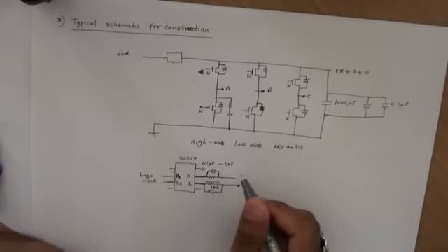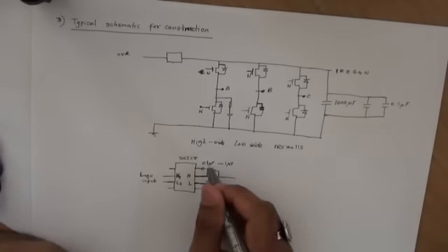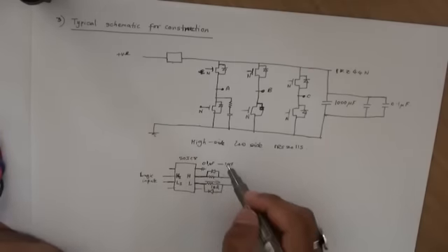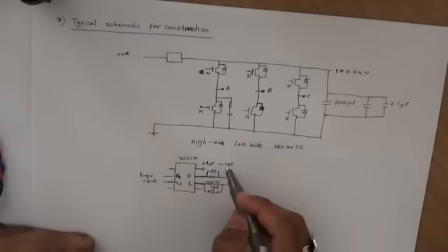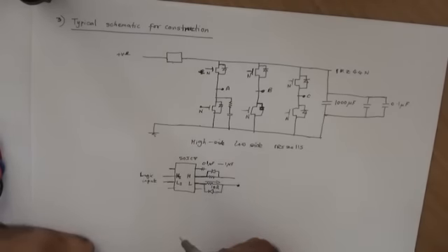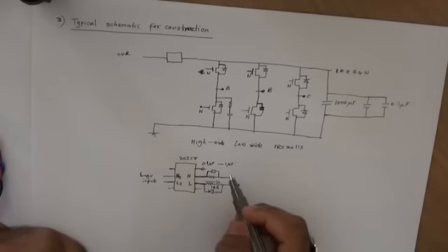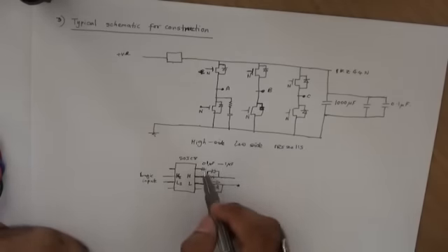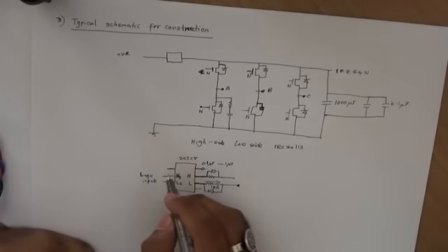If you're switching reasonably fast, you can go on to the lower scale, so you can have lower microfarad capacitance. If you're doing it slow, or your pulses are longer, then you need to have a higher capacitance as your charge pump. And depending on what your charge pump capacitance value is, you ideally want to have at least 10 times that as your filter capacitor across.